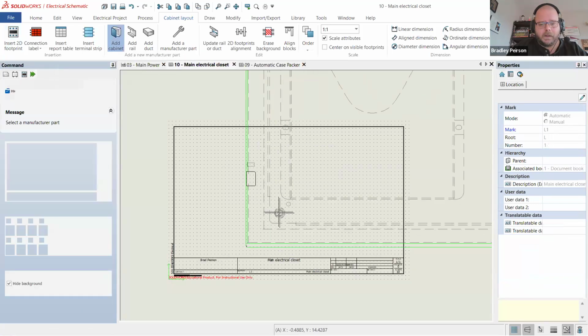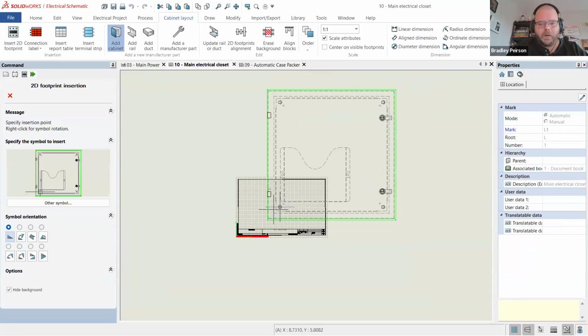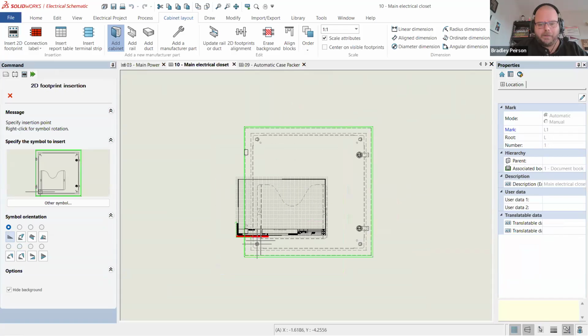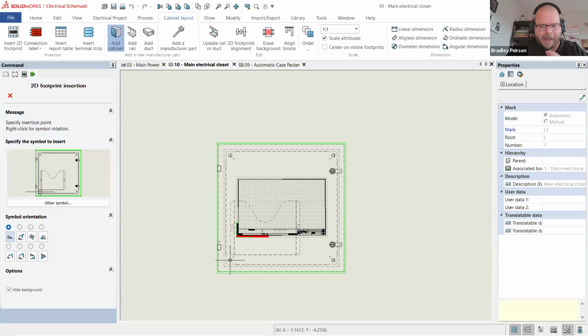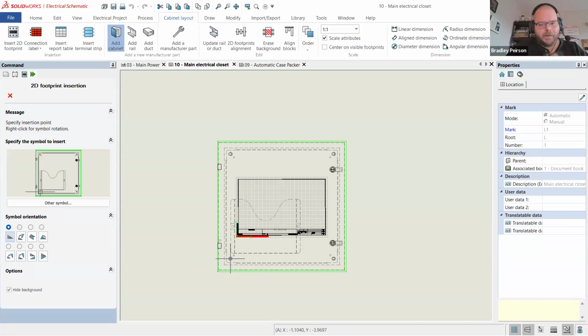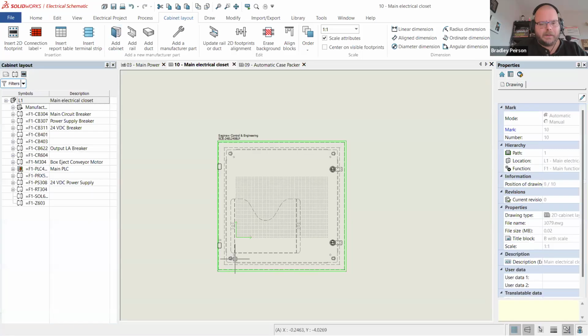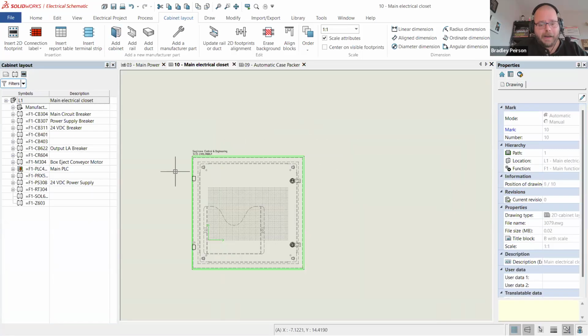Select. All right. Again, scale in the drawings is 1:1. So this box is way bigger than the sheet, which is fine. Again, I create it at 1:1, and then go about my business of drawing it and scale everything at the end. But again, our text scaled properly.